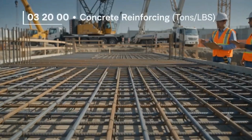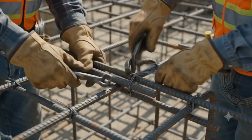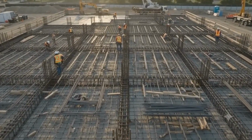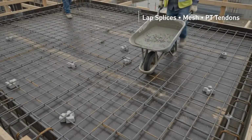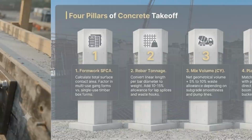Section 0320 covers concrete reinforcing, measured in tons or pounds. Your takeoff must capture rebar sizes from #3 all the way to #18. Don't forget to account for lap splices, chairs and ties, welded wire mesh, fiber reinforcement, and high-strength post-tensioning cable tendons.